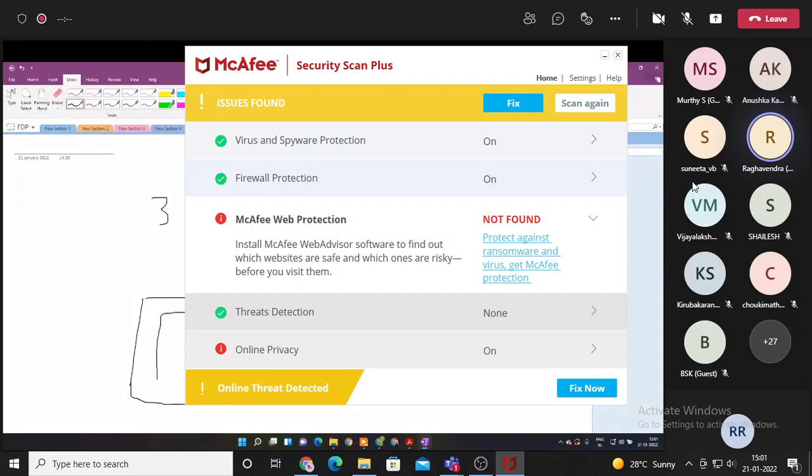One is the FPGA, followed by your ADCs or your DACs. You have two here, you have two here. Let's just assume this because you have I and Q, again I and Q, followed by which you have your actual RF front end, all of your mixers, local oscillators, filters, all of this. Anything that comes over here, that is the RF front end portion, is called the daughter board. And anything that comes over here, which involves the actual FPGA as well as the ADC, is called the motherboard.